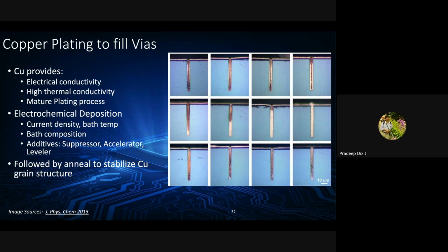If you look at this part, on the field, the copper deposition thickness is almost the same. I understand that these chemical additives, brightener, suppressor, and leveler, are going to influence something like the superfilling effect, right? But if you look at the field, there's almost no deposition taking place.